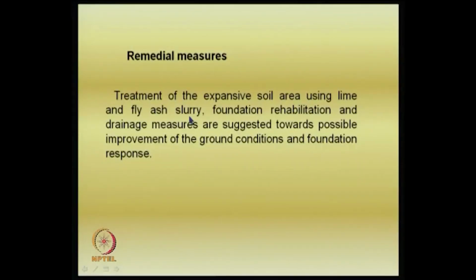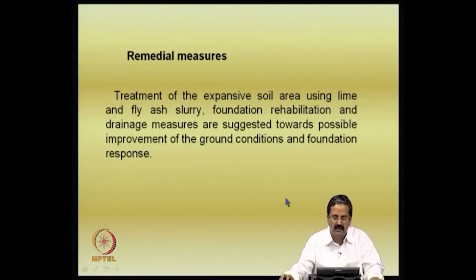Put some sandbags next to the foundation, use some pressing or remove soil, and whatever you do, confirm it from your measurements. You use your survey to see that it comes back to the actual required levels. Then the foundation treatment was done using the lime fly ash slurry with the following suggested rules, and it was expected to be satisfactory.